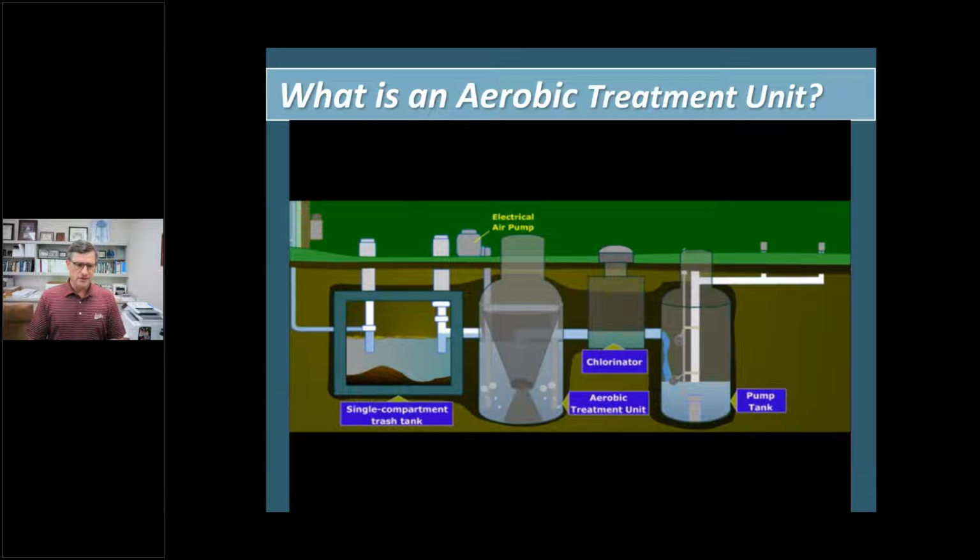It's no different than a chlorine contact chamber on a wastewater lagoon system. As the effluent is moving by, it's coming in contact with the chlorine tablets, rolling over into the pumping tank, and you hope there's a little bit of contact time for disinfection before it actually moves out. Again, chlorine is a phenomenal method of killing bacteria, given the right dose and given enough time.